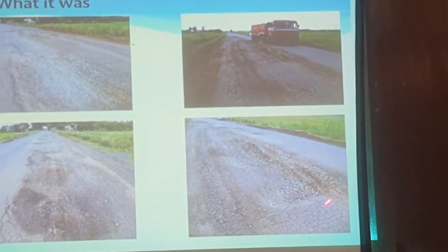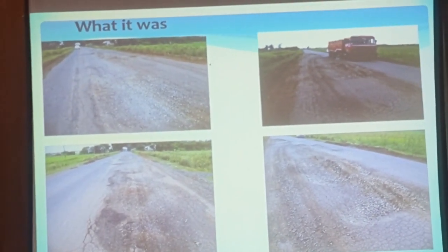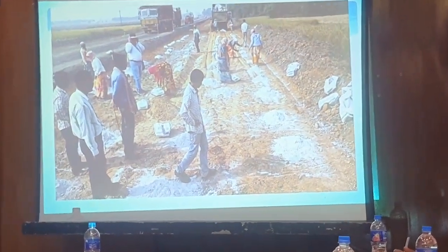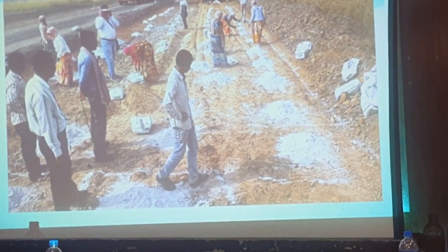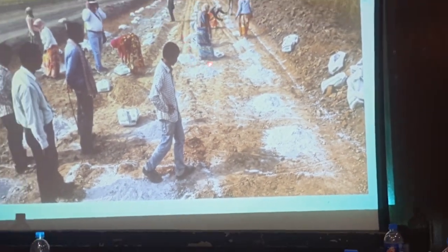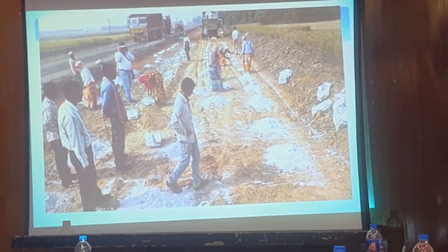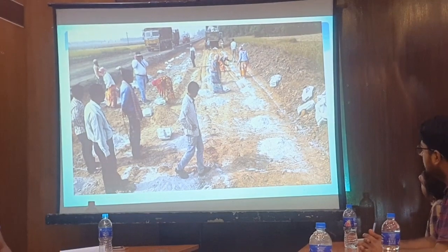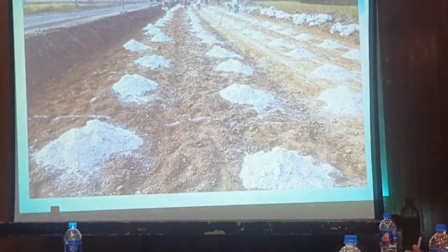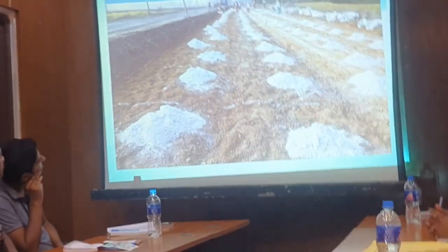This is a normal case of subgrade failure. After a lot of trying the conventional methods, this, that, it was done in 2015-16. It is RBI Grade 81, a chemical stabilizer, mixed with the subgrade at some design percentage. It's not lime, it is a chemical stabilizer, RBI Grade 81. Here it is mixed.